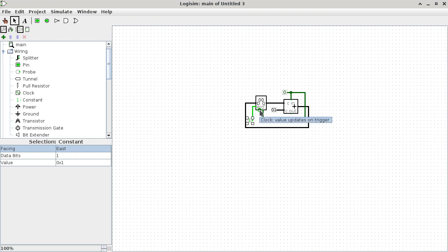So you can see that the circuit is not doing a single thing. The register stays put at the value of 0. You don't see it going crazy to 1, 2, 3, 4 all the way and then wrapping around again. It's not doing anything at all. That's because for a register, it needs the clock to go from 0 to 1. It needs a transition, a rising edge, in order to update its content. And right now, there's nothing here to specify a transition at a clock.